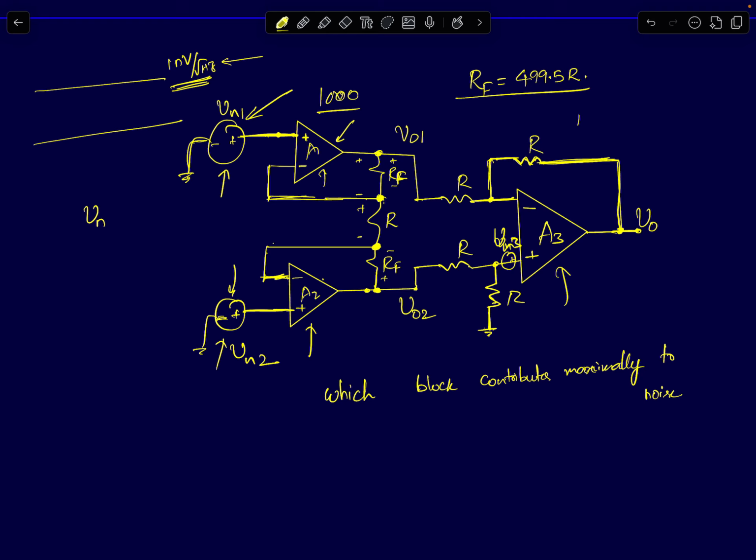Okay, so that's what uncorrelated means. The advantage of uncorrelated noise sources is that you can find the contribution of each noise source to the output, and then to find the overall spectral density you can just add up all three noise spectral densities. In other words, you can add their powers, because they are all white noise sources. You can add their power spectral densities too.